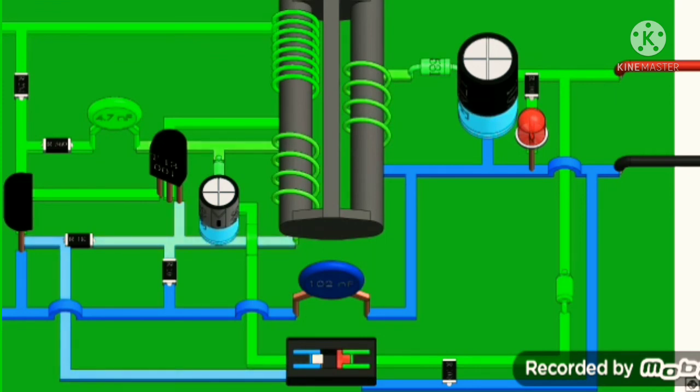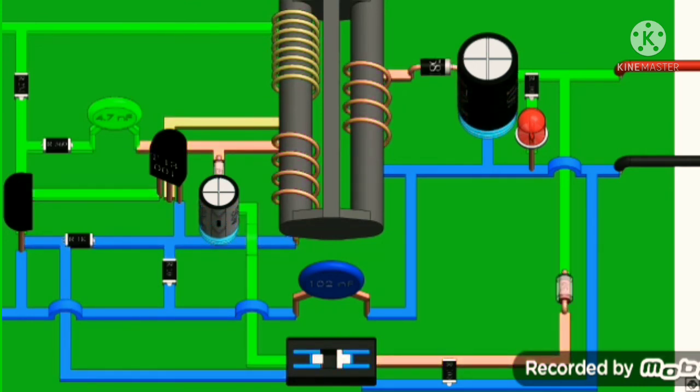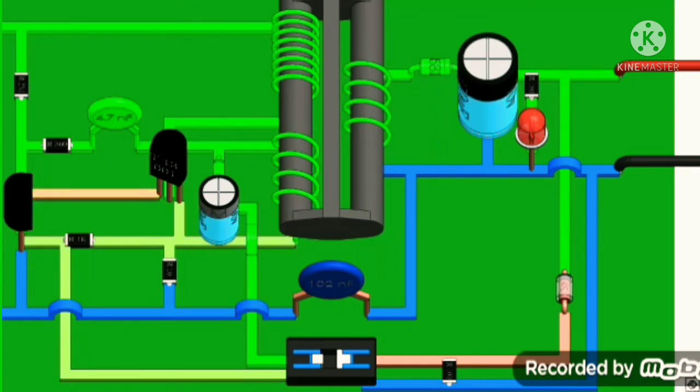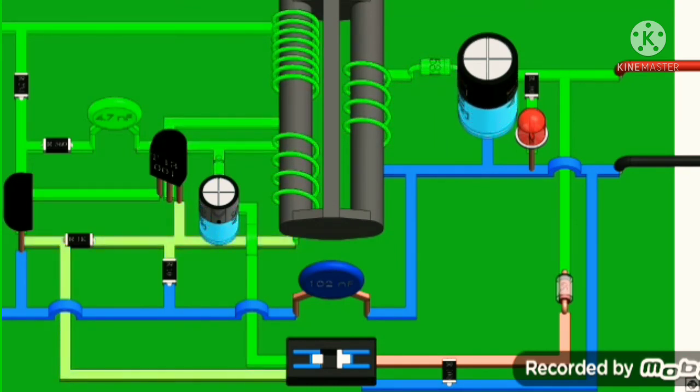The light of the LED turns on the phototransistor of the optocoupler, allowing the current to flow to the transistor T2. This turns on the transistor T2, shunting the first and stopping the flow of current in the primary winding. Also, the voltage in the secondary side of the transformer drops below 5 volts, turning off the Zener diode and optocoupler, and the circuit continues to run normally.